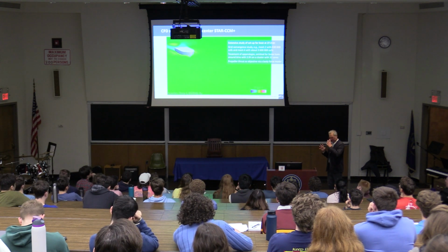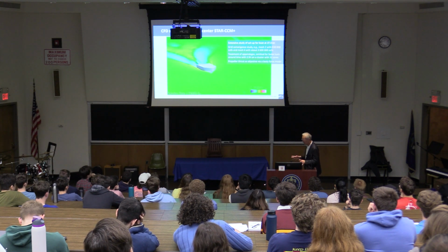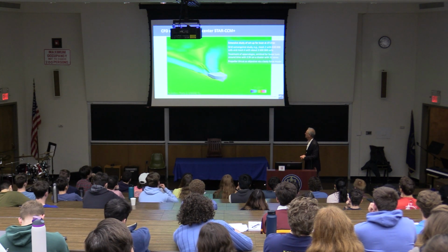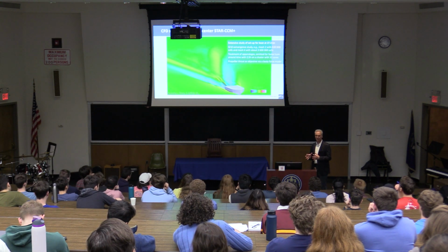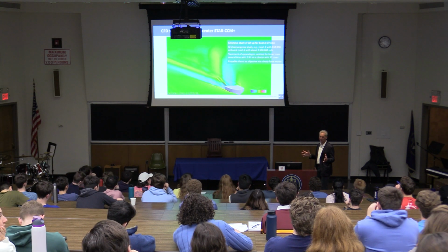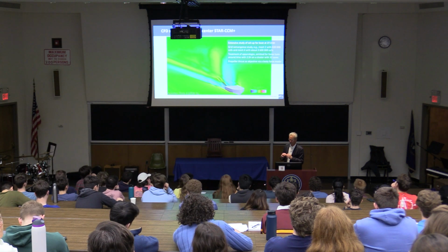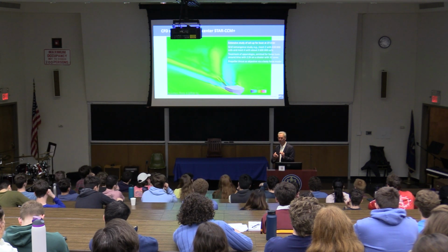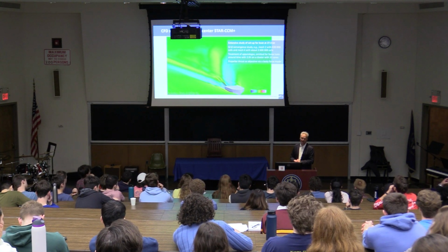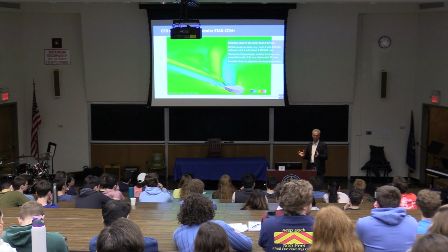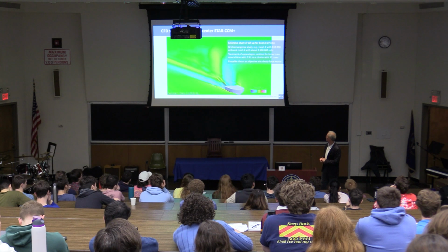So it's an overlapping grid technology with many cells, above 3 million cells that were spent. The overlapping grid helps you that you would have, with this reasonable number of cells, a very fine resolution of your free surface, of your pressure field around the hull in any case, and around the appendages. Okay, so very many cells very close, and then gradually go into fewer cells outside.